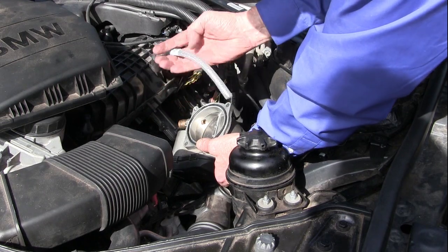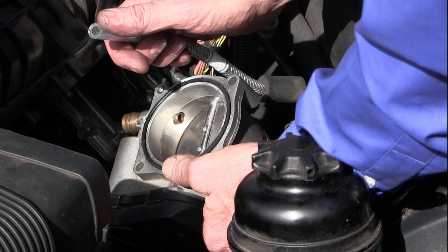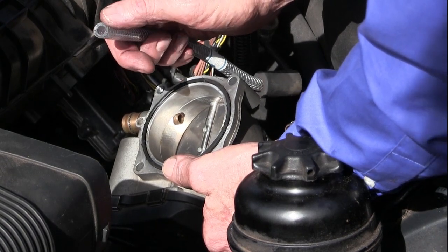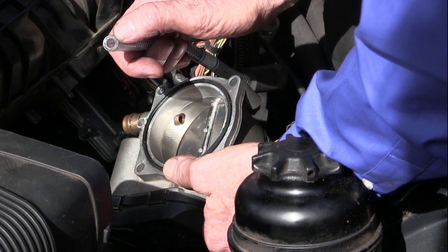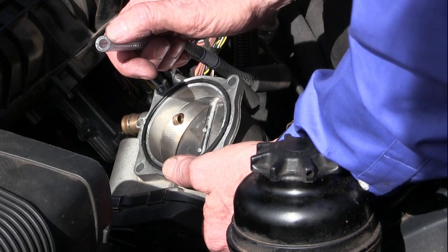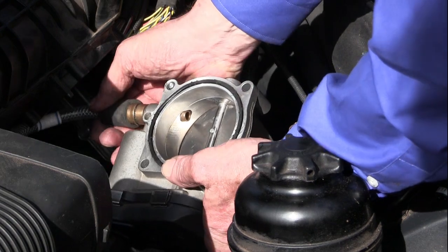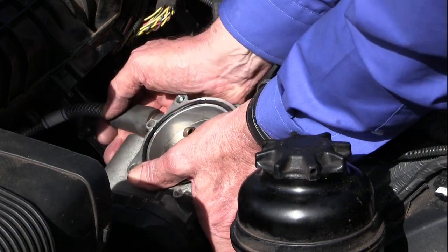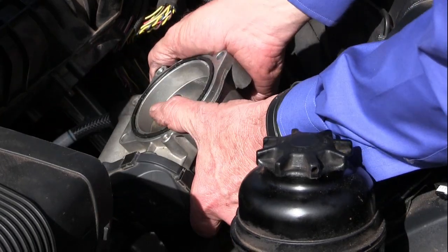These hoses are made of a special material that won't allow the chemical to stick to it, so it will blow through freely. Additionally, the inside diameter is very small, keeping the velocity of the chemical in air at a very high moving rate, so once it comes into the system, it will be carried and it will remain as an aerosol. Just put the hose on, and then you're going to put this back on.